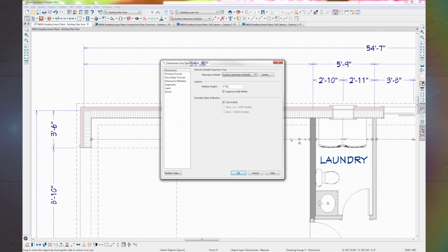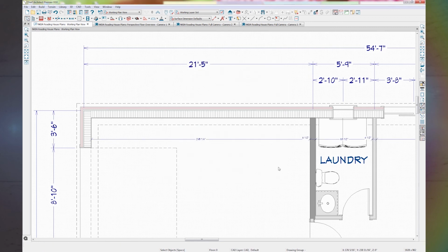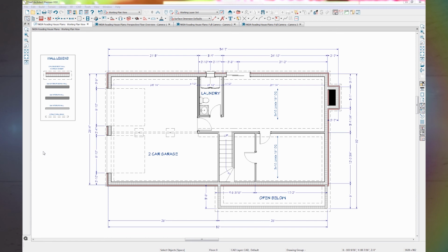If I turn on these dimensions for the interior wall, we'll also notice that the dark gray wall is 6.5 inches wide and the light gray wall is 4.5 inches wide. Because this thicker wall is part of the laundry room that has a toilet, sink, and a washing machine, it seems pretty likely that it's a wet wall and that there's plumbing and a soil stack in here with the wall framing. Let's look at some of the other walls in this drawing.